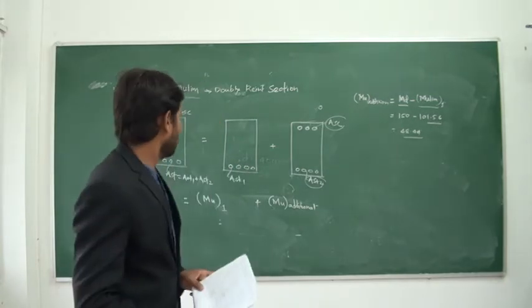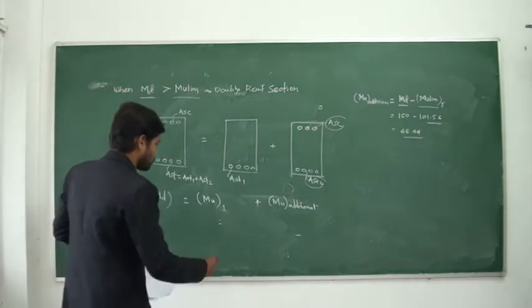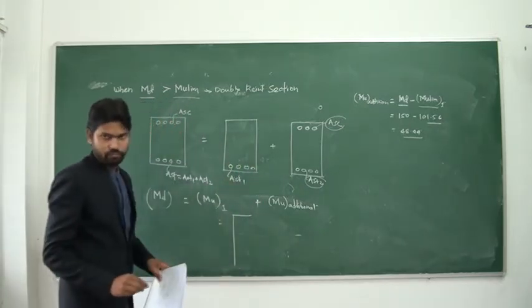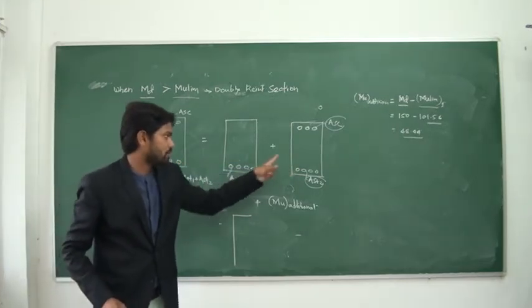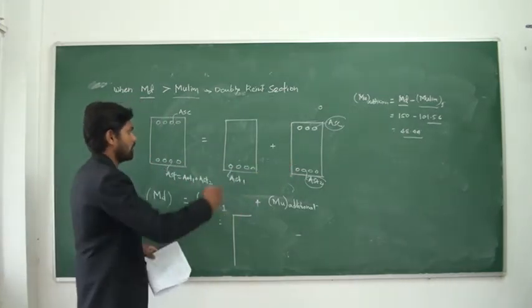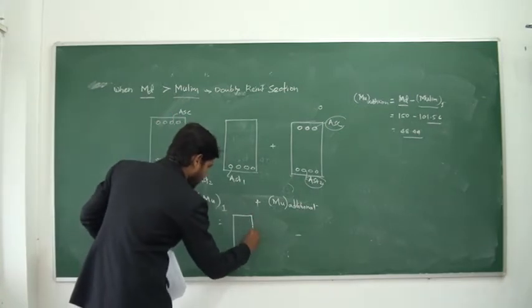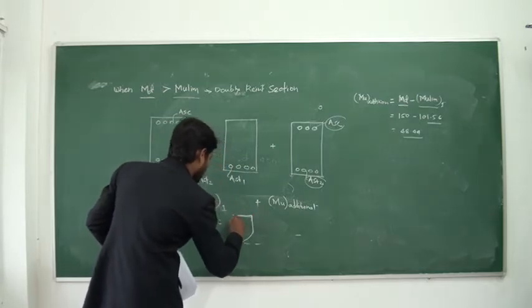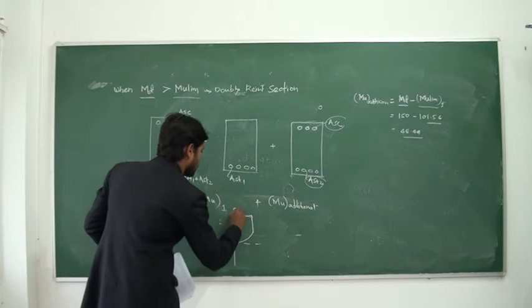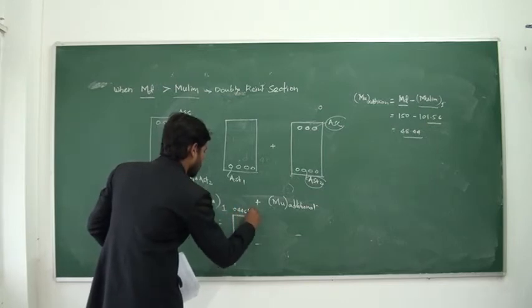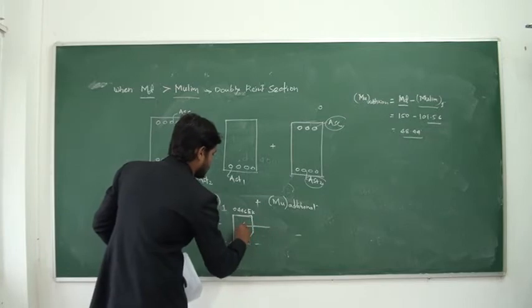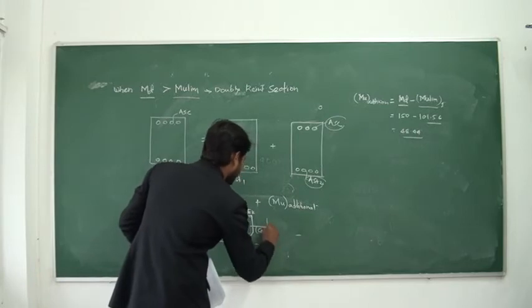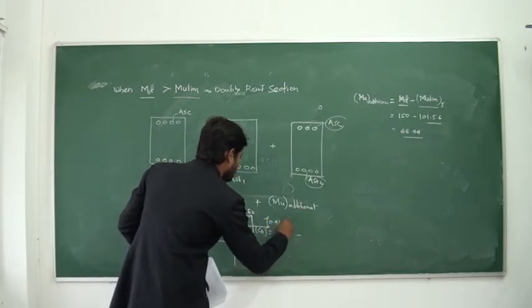Okay. So now, if you draw the stress block diagram of this particular case, this is your singly reinforced beam. Now this doubly reinforced beam I have divided into two parts. One is singly and this is double. And if you draw this stress diagram, this will be your usual stress diagram, 0.446 fck, and this compressive force will act at a distance 0.416 Xu.